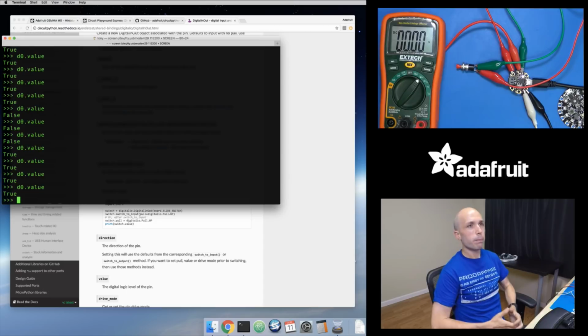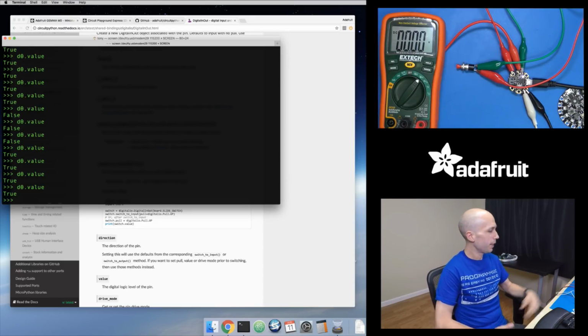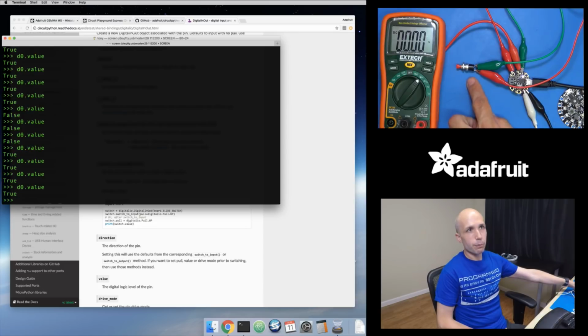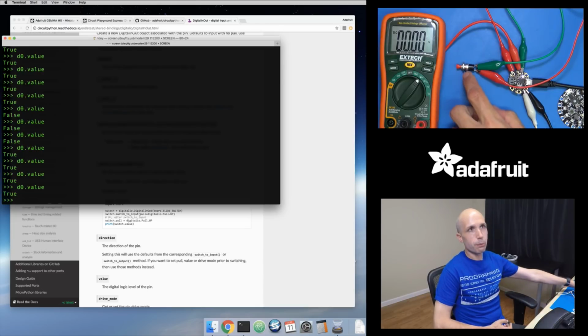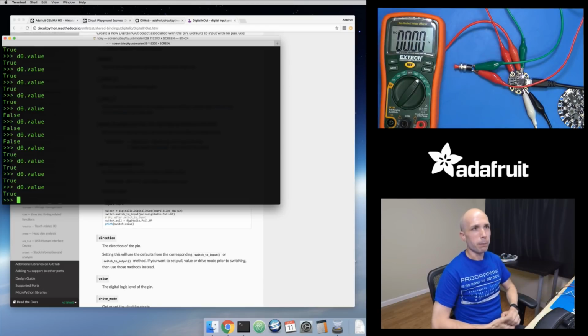So that's pretty much the basics of a digital input. I'm showing how to connect to a little momentary switch right here, and then by using the built-in pull up or pull down resistor, I can make it so that I can read this switch on this input by just feeding in either a high or low logic level, so that when the button is pressed, that logic level is connected to my input, and then I'll be able to read that value.